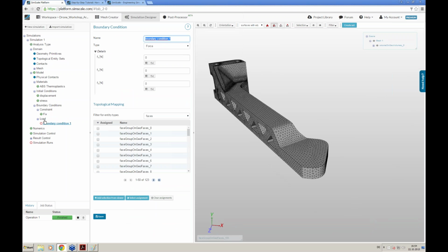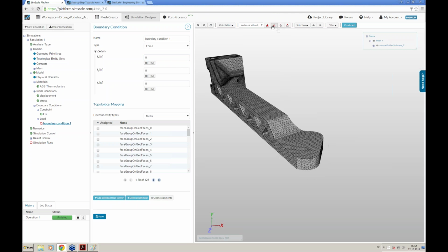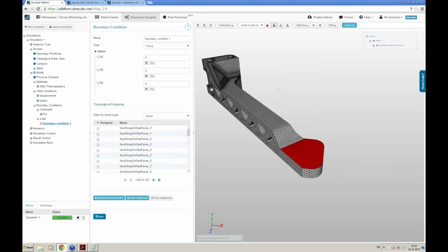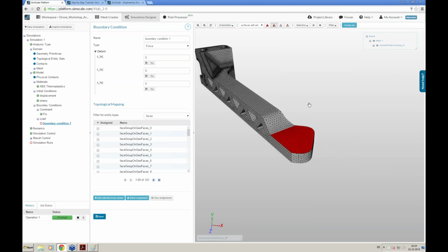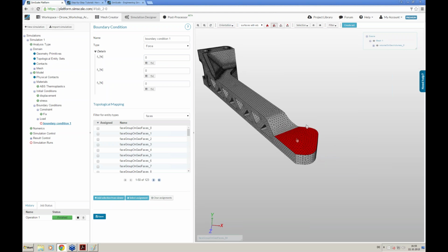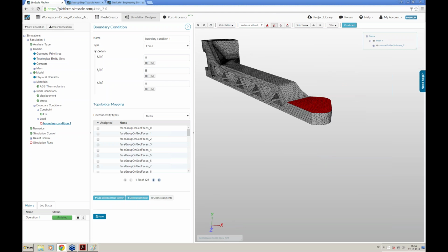Please note that it is really a load boundary condition, not a constraint boundary condition. Then we will again select the face we want to apply it to, and as a simplification, let's say on this whole face. So the force will be converted into a kind of pressure and applied on the whole face. The force on the surface is the value we add here, and yes, it's in the y direction, and I would suggest using 3 newtons, which is a realistic force, since we know from our last simulation projects about aerodynamics.